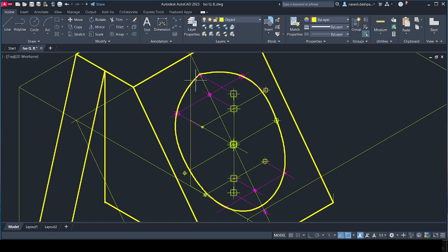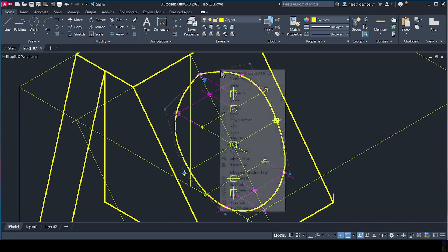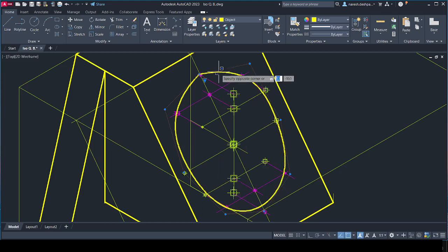You need to add an extra vertex. Okay, almost done. Little bit here. If you add one vertex, it will solve our problem. I'm not getting that option. Ah, here. Add vertex option is there. You can trigger this by right clicking on the available vertex. You can add extra vertex.